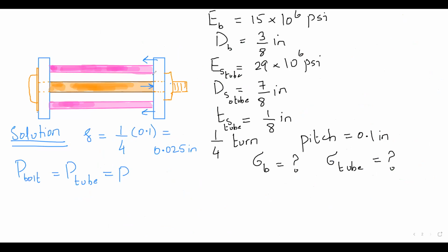Here the problem is, if I had told you that this is a rigid plate, that would have been a completely different problem. Right now what I'm telling you is, it's a hole. So this fellow goes through it and you are turning this. When you're tightening it, this whole plate with a hole in it wants to, let's say, go towards left.